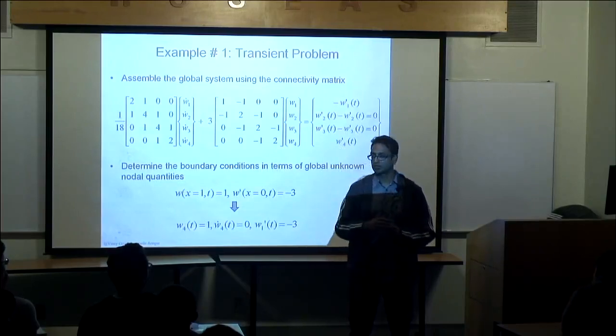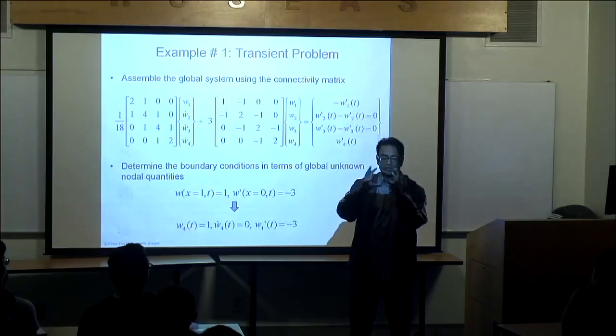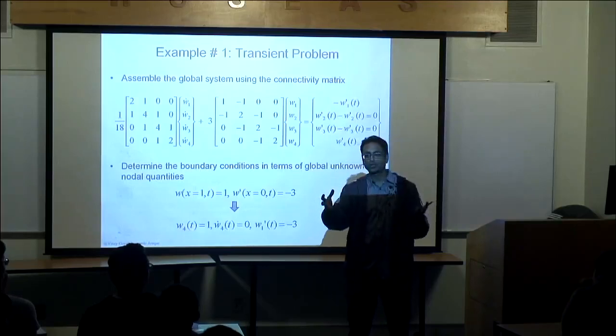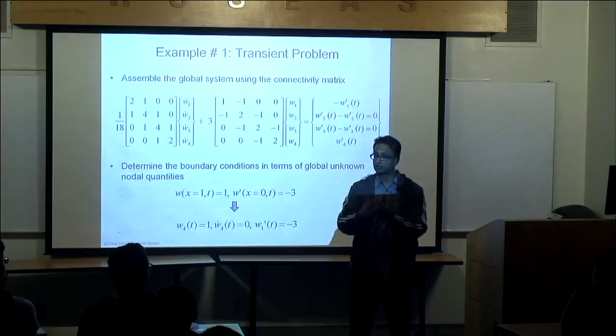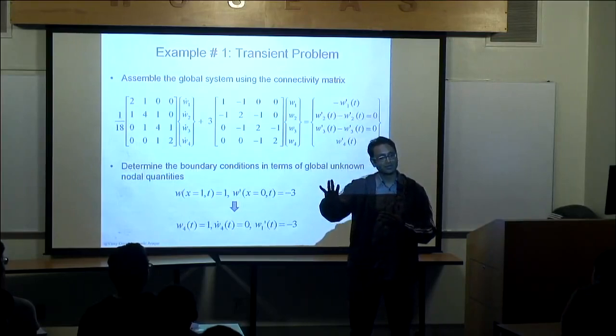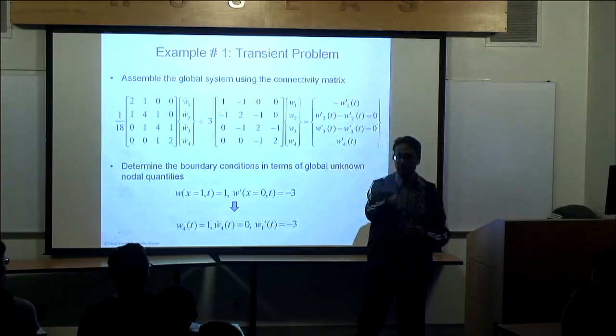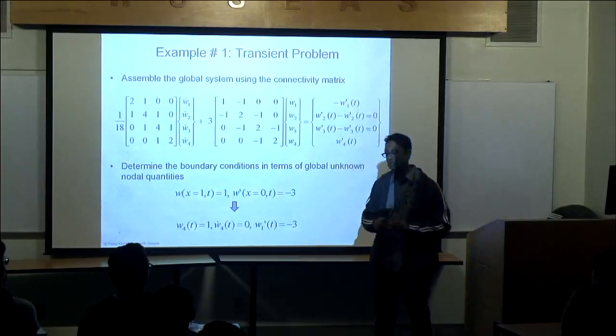The guys here in the back work in industry, they work on a lot of different problems, more than I do probably, and they can tell you more than I do. It's exciting to mesh it and apply the loads. You run it, and because the mesh looks so cool, you feel, man, I'm getting close to done. The mesh makes you lose touch. I'm just telling you from my experience. You realize, no, hold on, I'm not done yet. I have a lot more to do. The mesh may look great, just ignore that fact. Just trust me, focus on the boundary conditions and make sure those make sense.